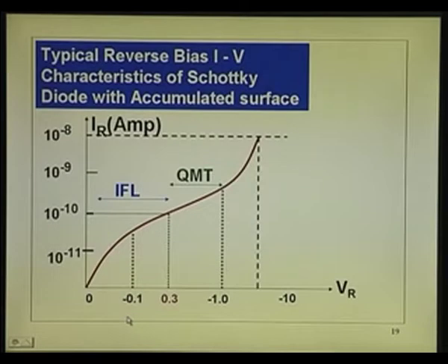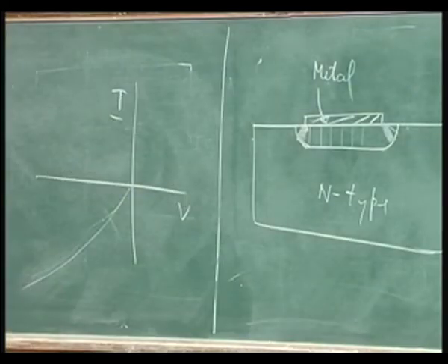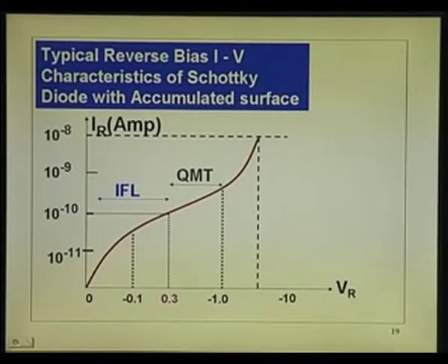Okay. This is of course a typical curve that you get. What I have plotted here on the board is shown here in typical devices that people have seen. So, you can see in this portion the current keeps on increasing, initially due to the image force lowering being dominant. But when you go to larger values of the electric field, larger reverse bias, the quantum mechanical tunneling takes over, and virtually it looks like a breakdown, like in a Zener diode. In the Zener diode, that is what is happening, it is tunneling. Okay. So, this portion is quantum mechanical tunneling, this portion is the image force lowering effect. So, both together it is very bad news, in the sense you get a poor diode.